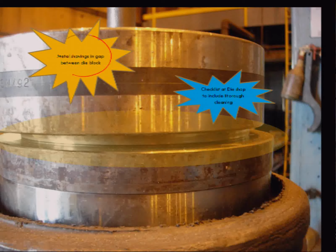Metal shaving, there was another issue of quality. How come in the die prep area, machining chips ended up between the inserts? When the alignment of the die piece is incorrect, boom, what you get is a broken die, maybe a broken machine, definitely a bad part. So the checklist is very important, covering the dies to prevent chips from entering spaces.